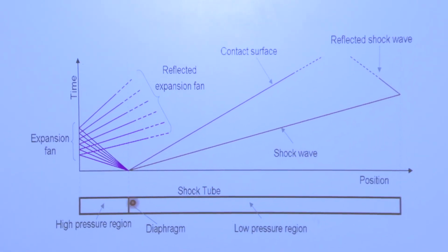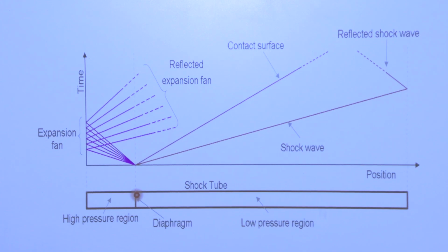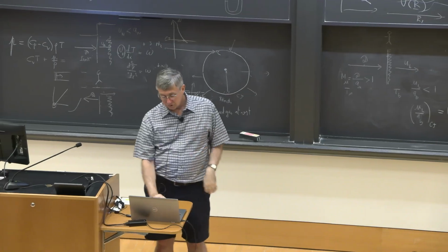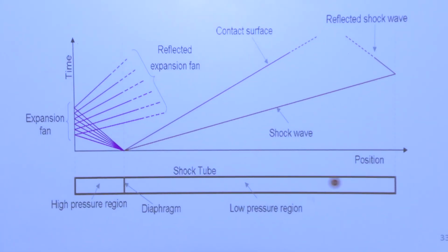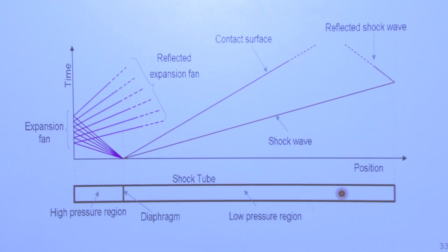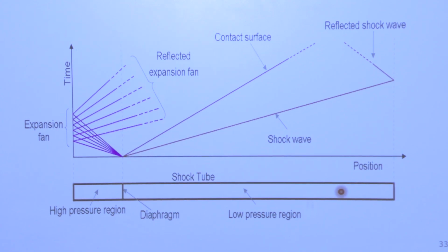And you'll suddenly have high-pressure gas touching against low-pressure gas with a very sharp, abrupt drop in pressure. That pressure discontinuity is a shock, and the shock will propagate down the tube. And when the shock passes a region, the shock compresses the gas there very suddenly from low pressure to high pressure. And it's basically an adiabatic compression, so the temperature goes up a lot. Because just like in a piston, if you suddenly slam a piston closed, the gas gets hot. The same thing happens here. So the gas gets hot.